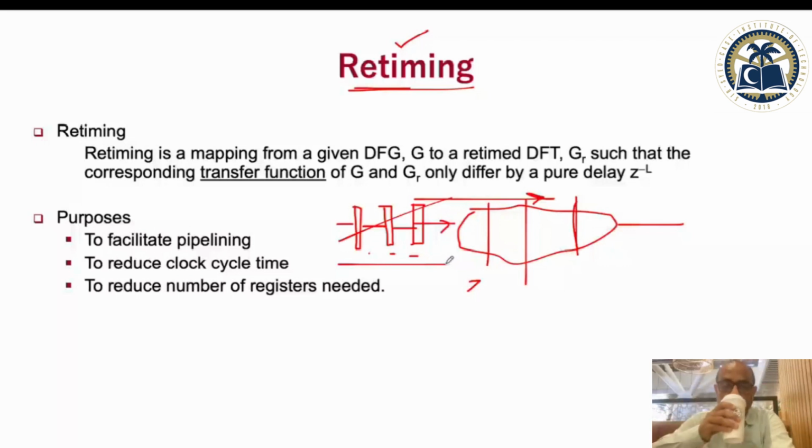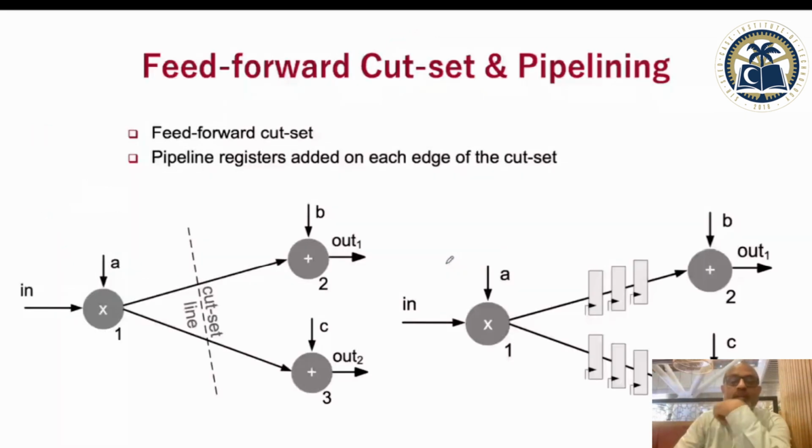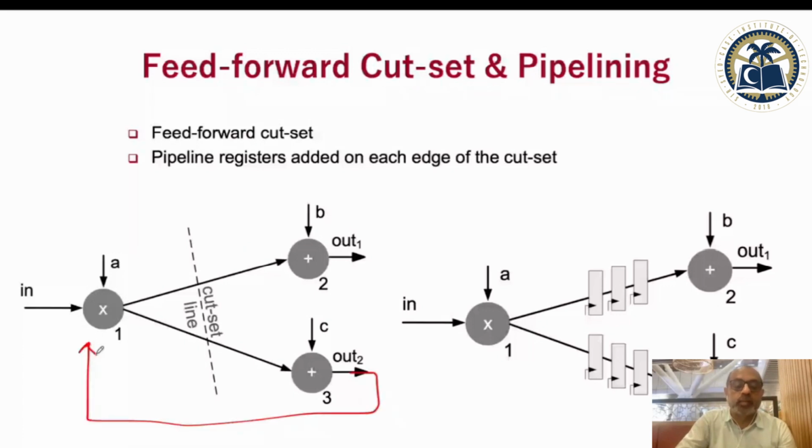So this is a very interesting way of looking at pipelining. Pipelining usually is for feed forward circuits, where nothing is fed back into the design. For a feedback circuit, adding a register inside the combinational cloud will change the difference equation, will change the order of the difference equation, because once you have a feedback system, if it is a discrete system, it is implementing a feedback loop.